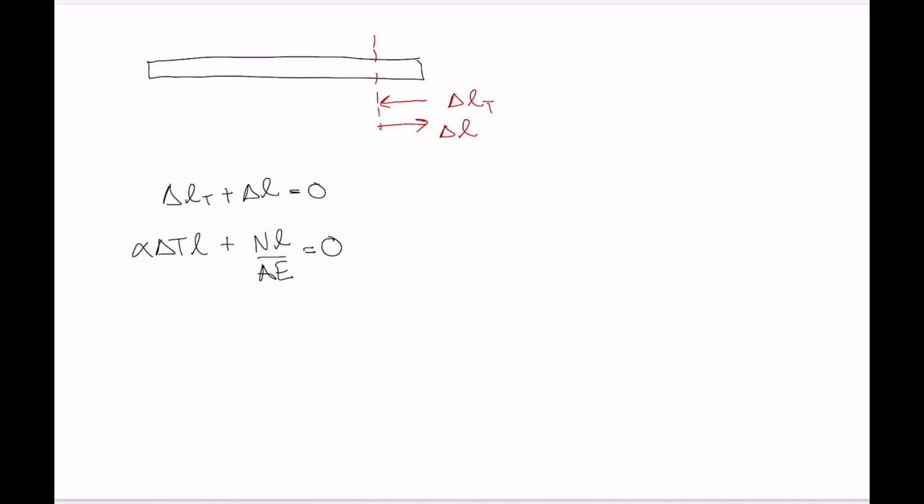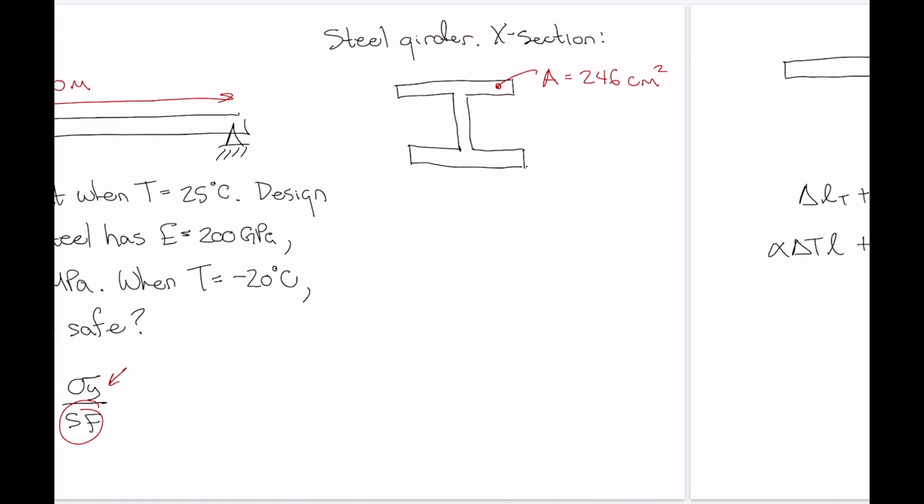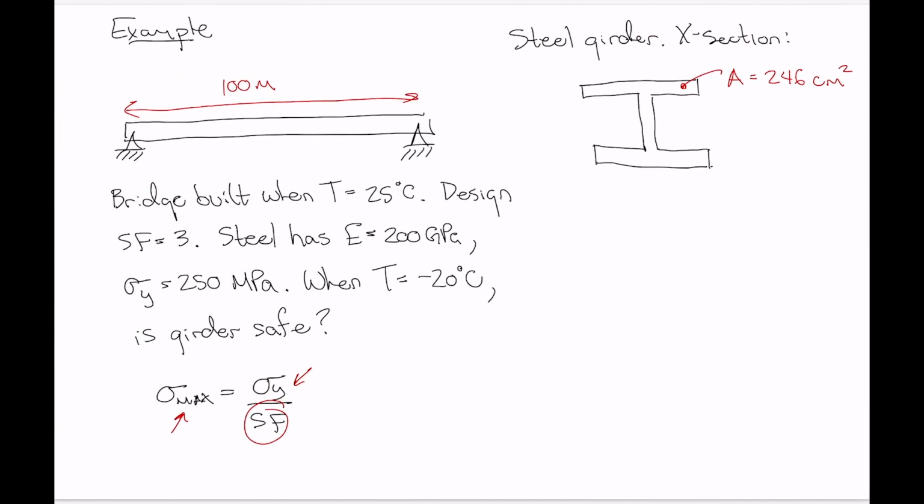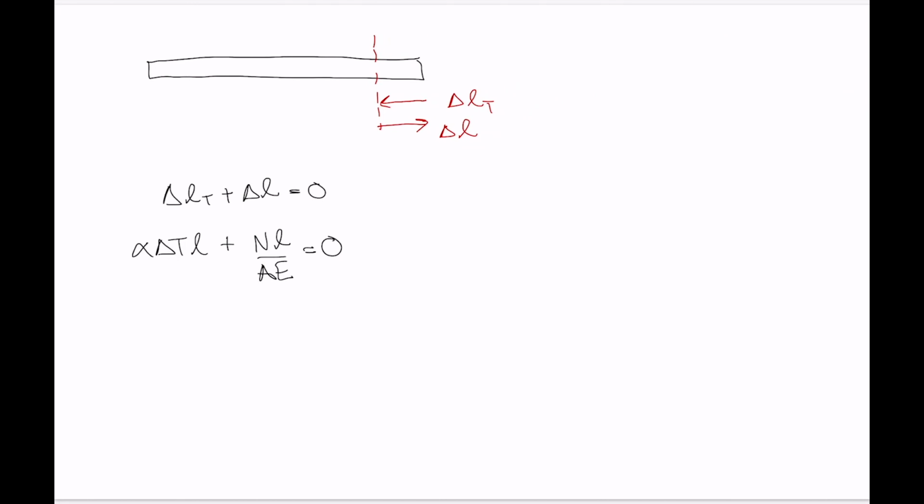Now, looking back at the previous page, we know that we want the current stress in the object, and stress is N divided by A. So that term appears right there, so we can substitute sigma in and not worry about getting our normal force out of this expression and then having to divide it by the area to calculate stress.